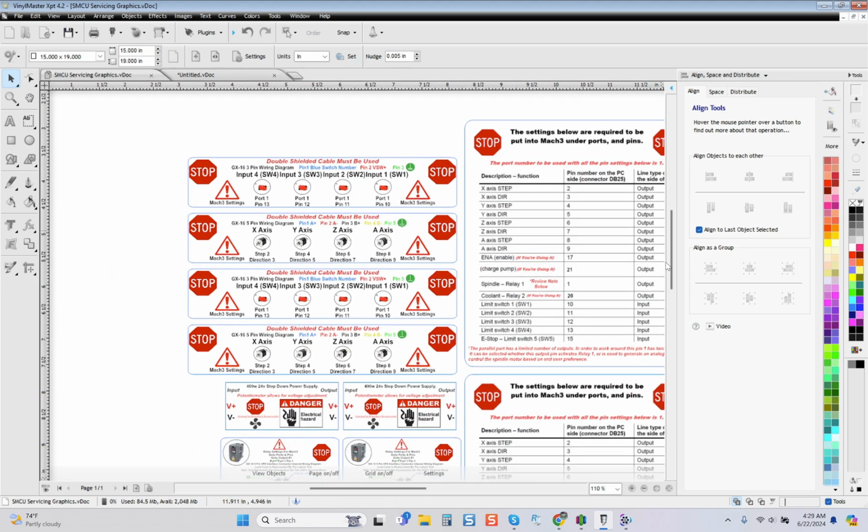This will actually mitigate excessive amounts of support required, because you'll have the information on the controller for you to access your system. You can see here we've got port 1, and this is for all of the switches, and then we have the pin allocation in Mach 3 for all of our 4 switches. Okay, and you can see here I even put the wiring diagram on here. I can tell you right now, like many of you already know, there are no vendors that do that.